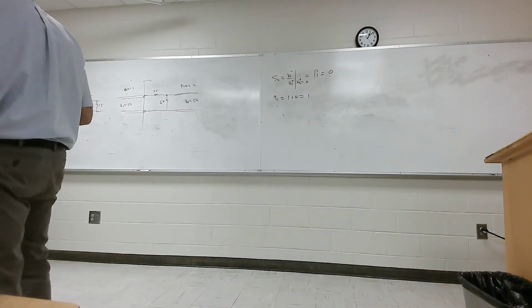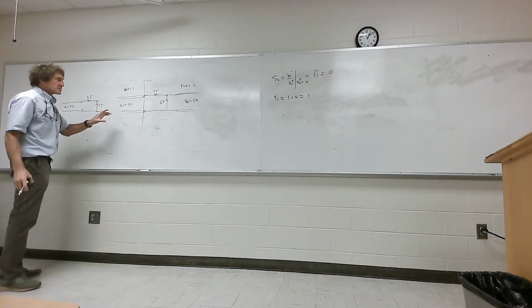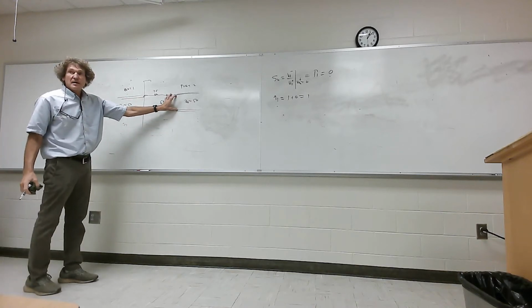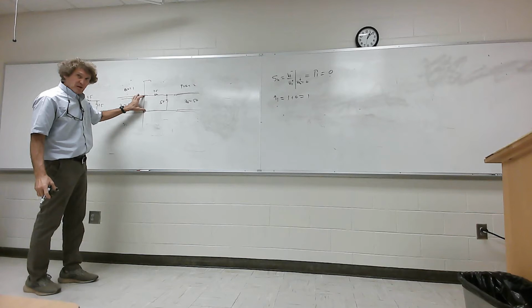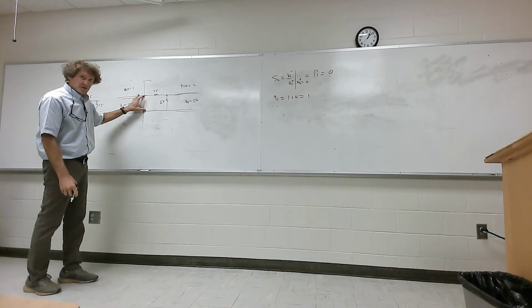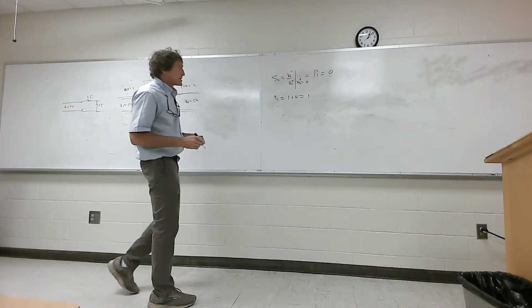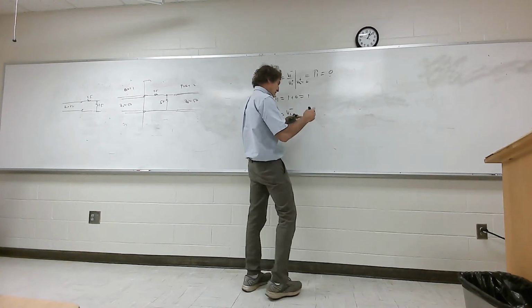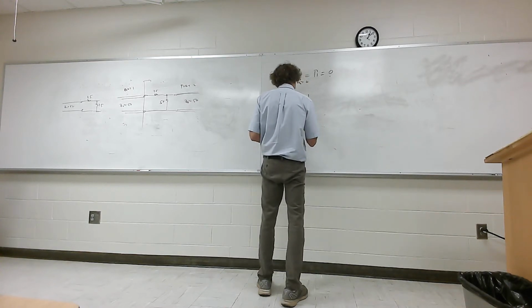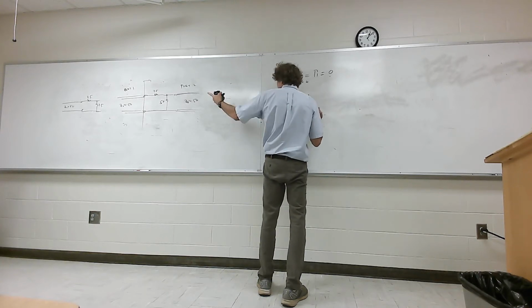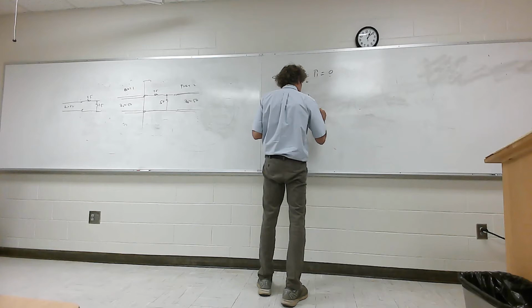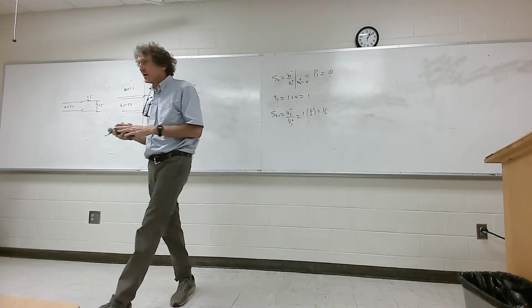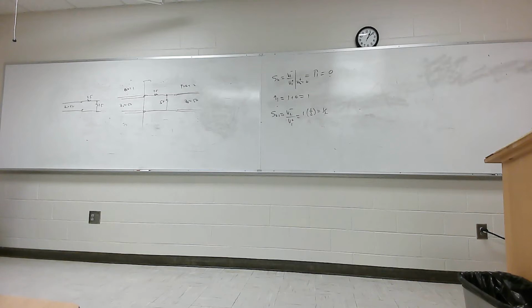Now, of the signal transmitted, how much of this signal that's transmitted is developed over here? Simple voltage division. Take V1 plus, right? All of it's transmitted. And then what? It's just 50 over 100 times that. Correct, class? So that means when I look at this, S21, which is V2 minus over V1 plus, what I have to do is find the transmission coefficient, which is 1, then times the voltage division, which is going to be 1/2, so that's equal to 1/2. Does everybody follow me? The reason. Think about it just by yourself. Make sure you can convince yourself. Y'all follow me on this?